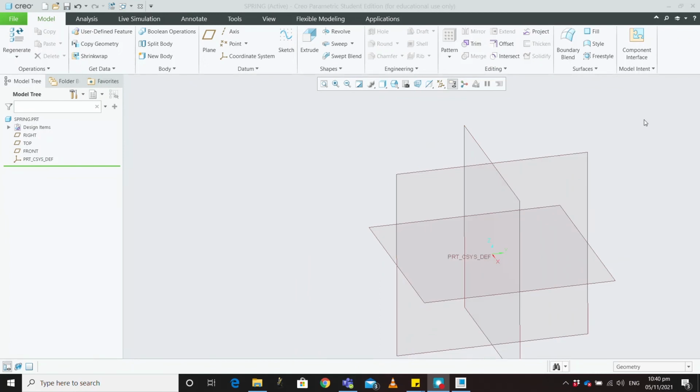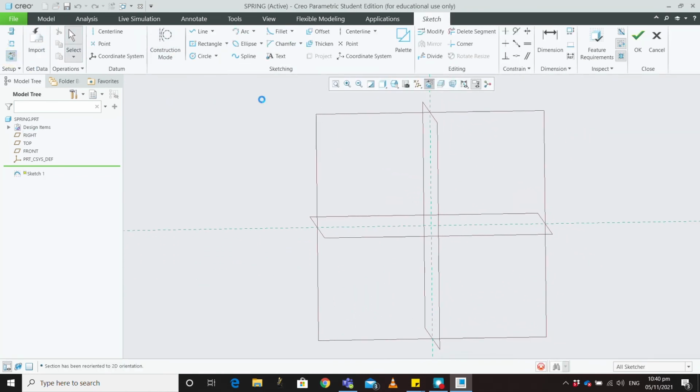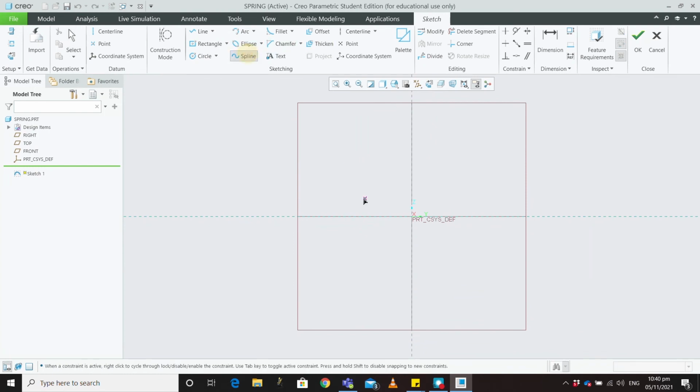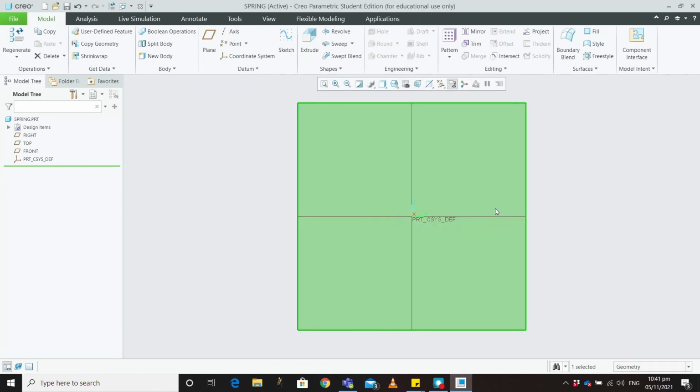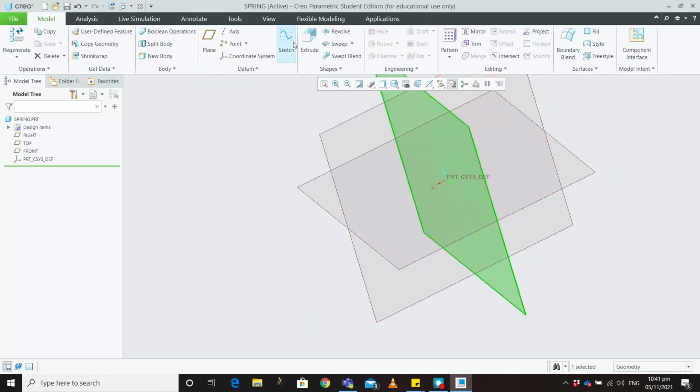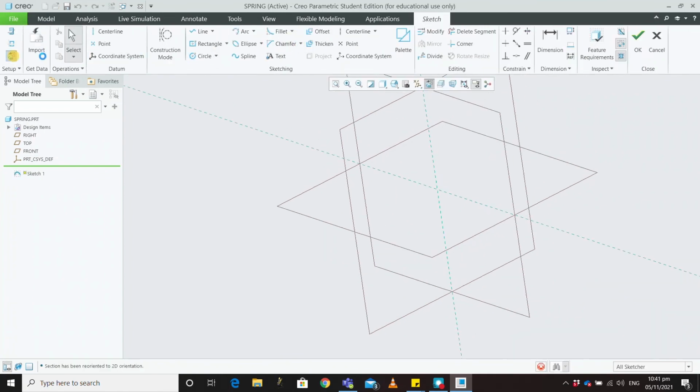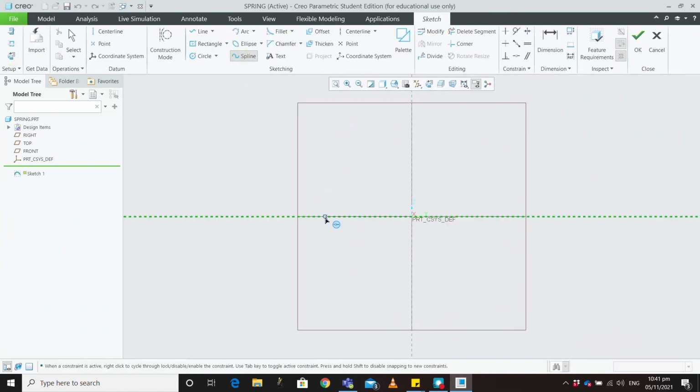Now all of these were regular shapes, but what if you have some shape which is arbitrary, for example, something moving along a path, maybe like this, a random path, whatever. And let's even use this shape we have done. I'll remake that. So what I've done over here, I've just selected a plane and clicked on sketch, and inside the sketch mode I define the path of my shape, whatever it is taking. It can be anything. For the same reason I'm using a spline over here, because it creates the most random shape.